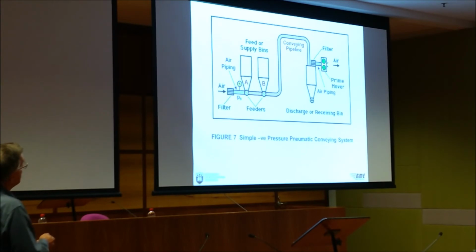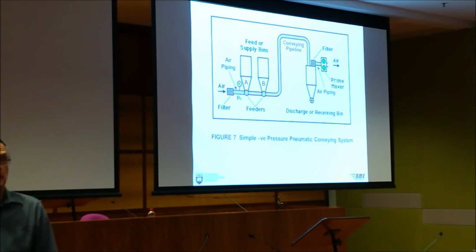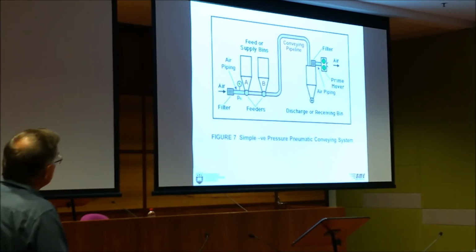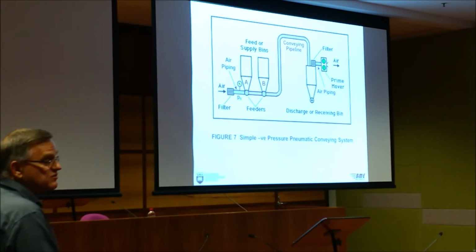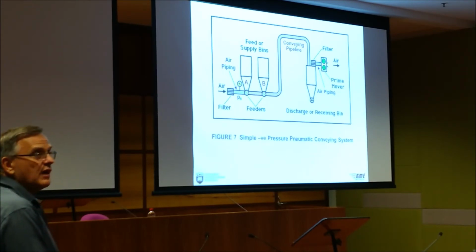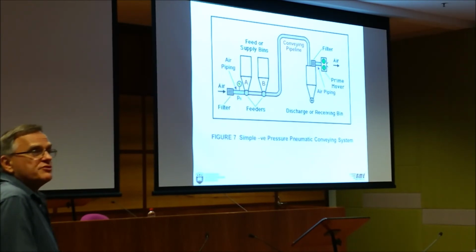So if we're talking about putting a pressure gauge on here, what would that read? That pressure gauge. What do you reckon? Yeah. Because you're sucking in air from ambient, there might be a small pressure drop across this, not much, but the air pressure inside that bit of pipe there is pretty close to atmospheric pressure. So the gauge pressure is 0.